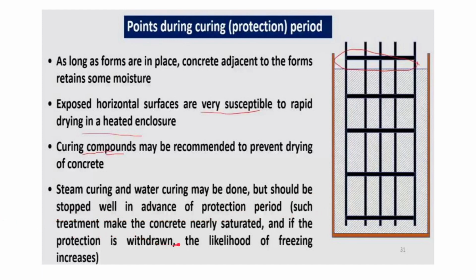Steam curing and water curing may be done, but should be stopped well in advance of the protection period ending. Such treatment makes the concrete nearly saturated, and if the protection is withdrawn, the likelihood of freezing increases, because due to water curing and steam curing the concrete becomes saturated. At that time the freezing condition will increase. That is why it should be stopped well in advance of the end of the protection period.